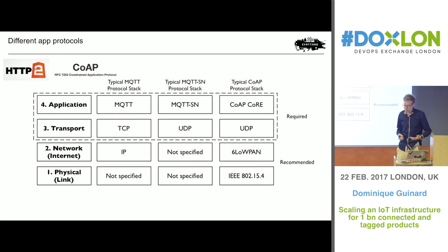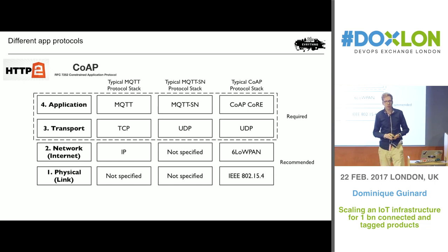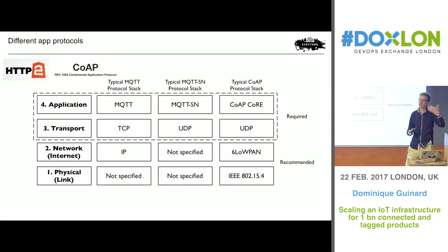So there is also here really a meaning in using these different ones. Okay, you also have different app protocols, and again here the same thing, these application protocols, right? I'm a big advocate of the web, as you'll see later on. So I would say if you can, use a web protocol on your embedded device. But if you can't, again, for the same reason, usually power consumption and cost, then there are some nice alternatives. MQTT is one that was developed years and years ago by IBM. It's a great protocol for IoT, and it bridges very easily to web and internet.